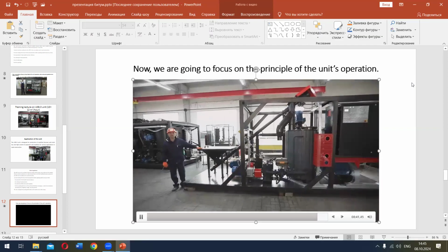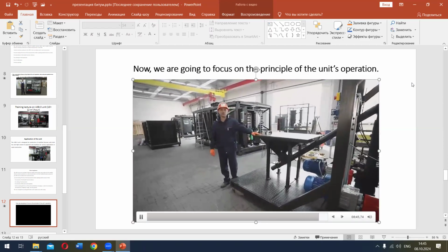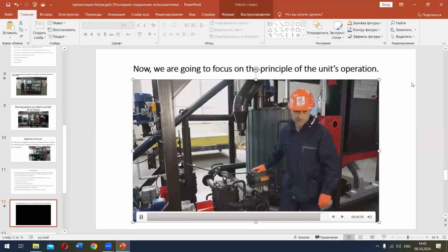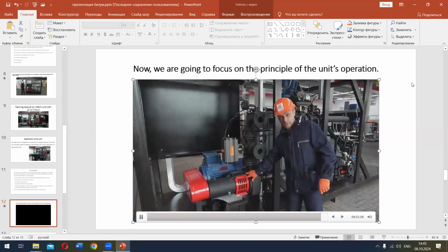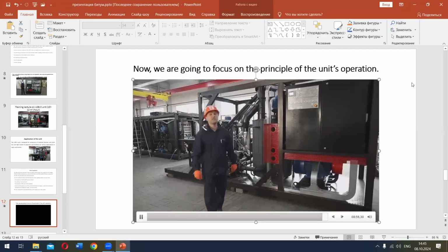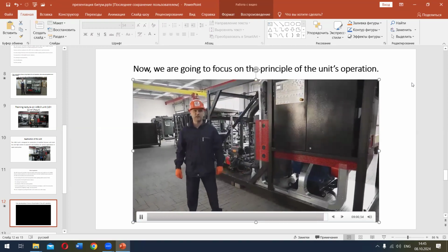The polymer input component can be equipped with a monorail hoist comprising a weighing system for supply of big bags. The pneumatic valve control system can be supplemented with a compressor. The mill can be completed with a mechanical seal. Therefore, the unit constitutes a simple, reliable, and efficient complex for manufacturing almost any products in bitumen modification.